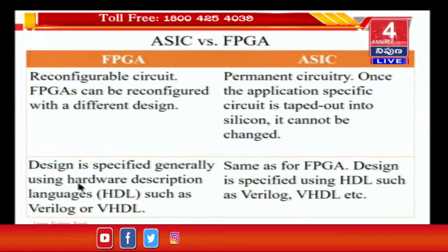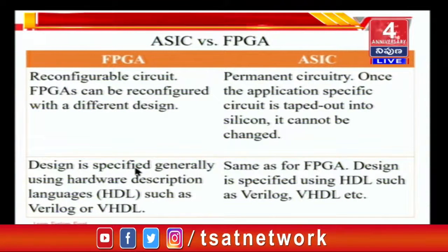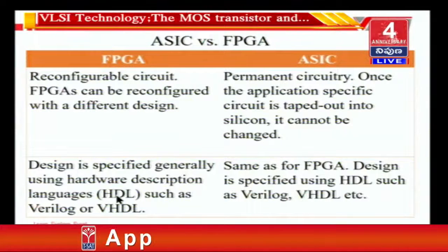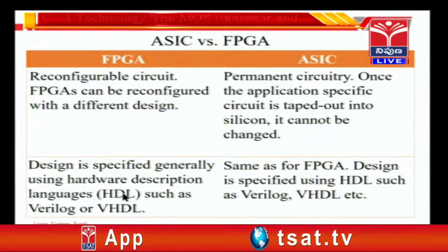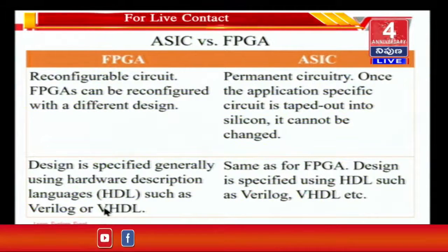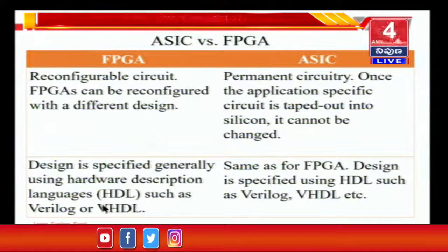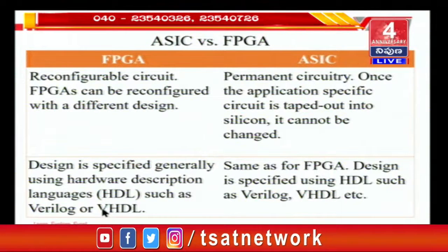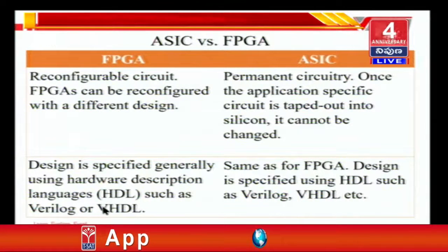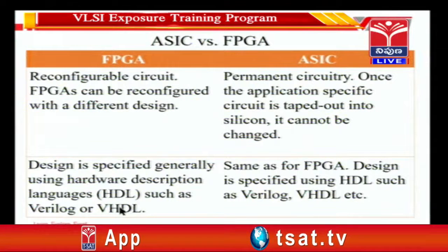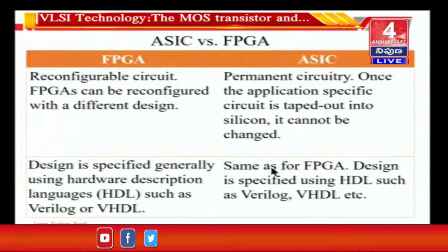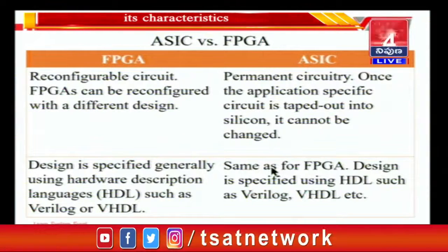The second point of comparison is that design is specified using hardware description languages, about which we will talk a little later. HDL they call hardware description languages, such as Verilog or VHDL. Don't think that VHDL stands for Verilog HDL. No, VHDL is a short form for very high speed integrated circuit, VHSIC, hardware description language. That is VHDL. For FPGAs also it is pretty much the same, and you do the design using Verilog and VHDL.